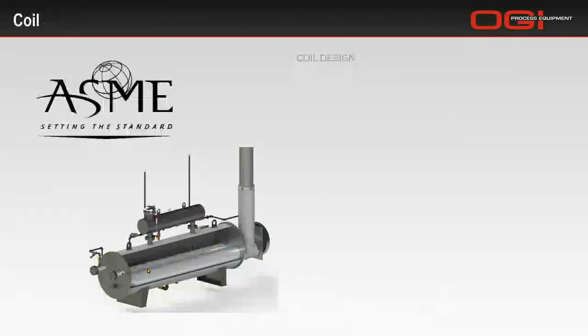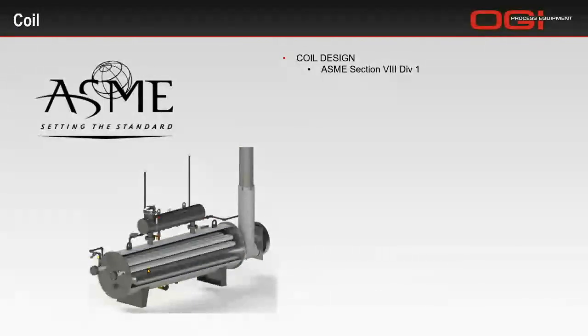Next, let's take a look at the coil design. Like I said, this is what makes your heater a pressure vessel per ASME Section 8-1. And again, you should be getting a U stamp on this heater, which also means that you should be getting a code data book from your manufacturer with all the MTRs, with all the testing, hydro testing, with X-ray, and